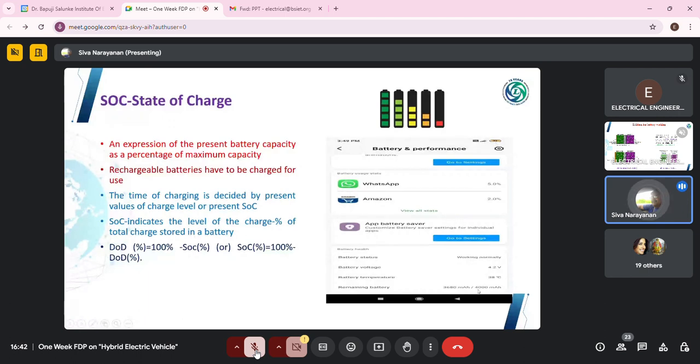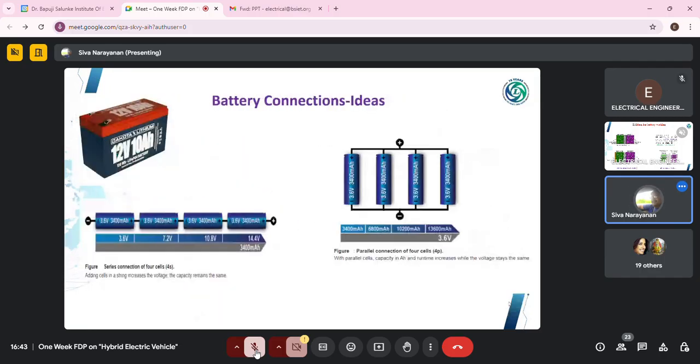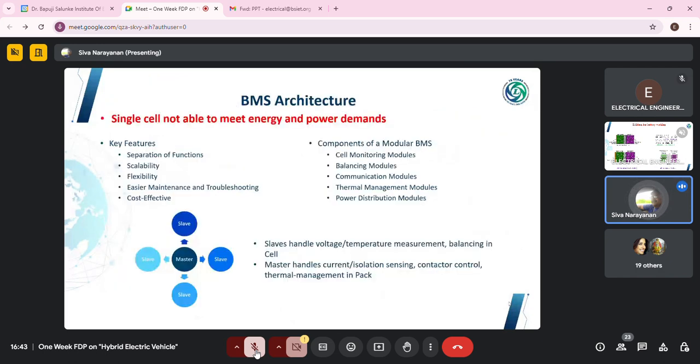So 100% of my battery is 4000 mAh, and now it is showing 92. So it shows that the remaining battery is 3680. It shows that 8% of my charge has been used. So the remaining 92% of the charge is left. Thus SOC indicates the current charge available relative to the total charge available. So this is what is done by our algorithm. It estimates the ratio: what is the current charge available?